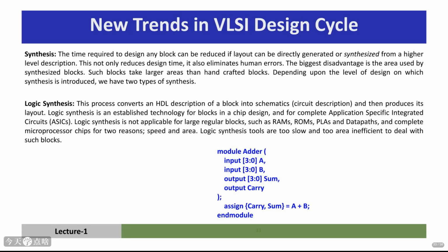Synthesis. Instead of manually designing every transistor, can we automate it? Logic synthesis is a mature technology that takes a high-level description, like Verilog or VHDL, and automatically generates the corresponding circuit diagram, the netlist. It's widely used for smaller blocks within a chip. However, it struggles with large, regular structures like RAMs or entire microprocessors due to speed and area inefficiencies.